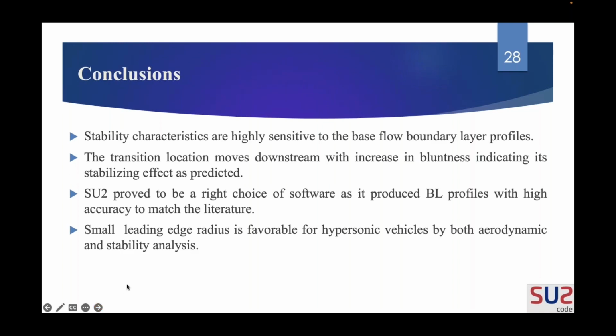So to conclude, I have focused on the flow features and the trends that we see when we increase the bluntness. I've also explained how we can see that the transition location varies downstream when we increase the bluntness. We have also seen how the stability characteristics are affected by the bluntness.